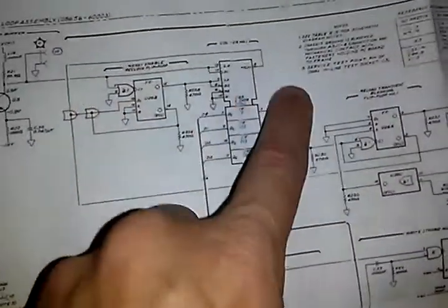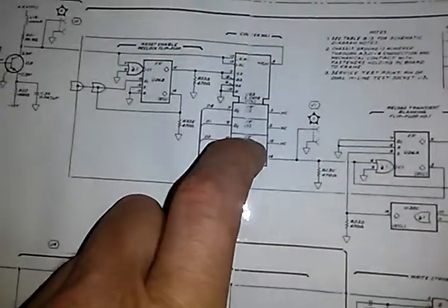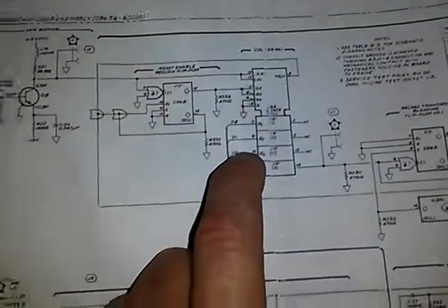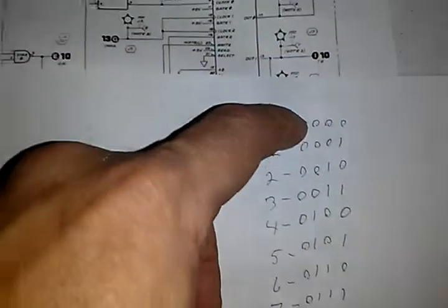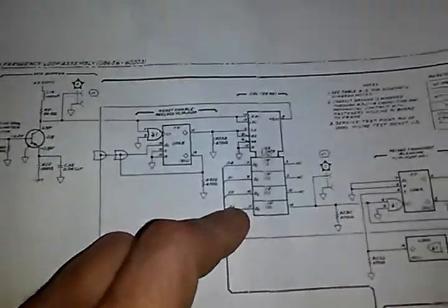Now, as this line is held high, after the first count, when it's loaded and it counts to this terminal figure, it basically just rolls over to 0, counts to F, rolls over to 0, counts to F, which in effect operates as a divide by 16